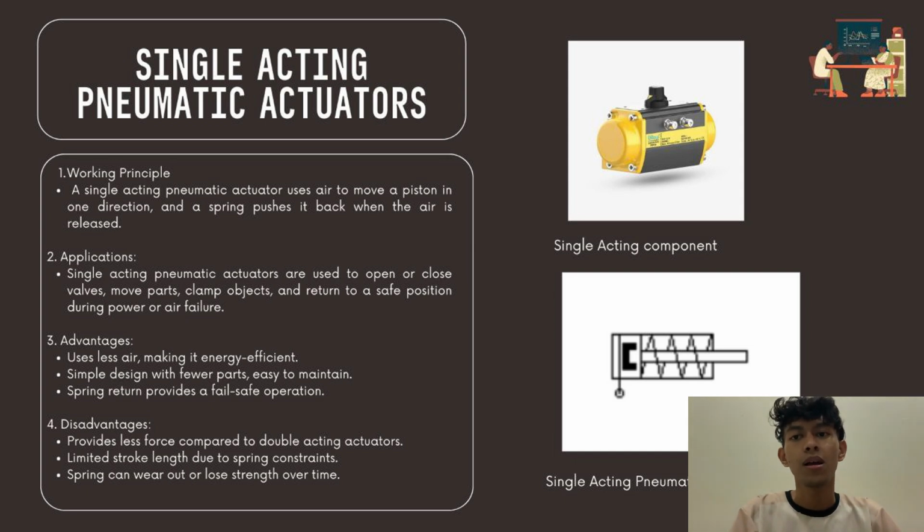Disadvantages. It provides less force compared to double-acting actuators. It has limited stroke length due to the spring's constraints. Lastly, springs can wear out or lose strength over time.